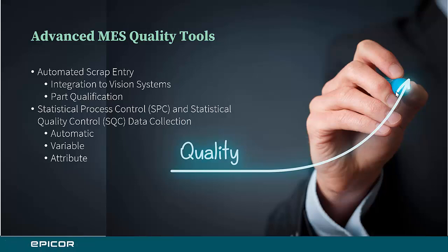And I want to statistically be able to say that, hey, it went outside of a control limit, it went outside of a spec limit, I'm shifting, I'm trending. And as those conditions happen, I want to do adverse things in our system. And one of those is called part qualification. And what that means is that I'm relying on those process conditions to tell me if that's a good part or a good shot, and I want to automatically scrap that if it deviates from that. So that's called part qualification.